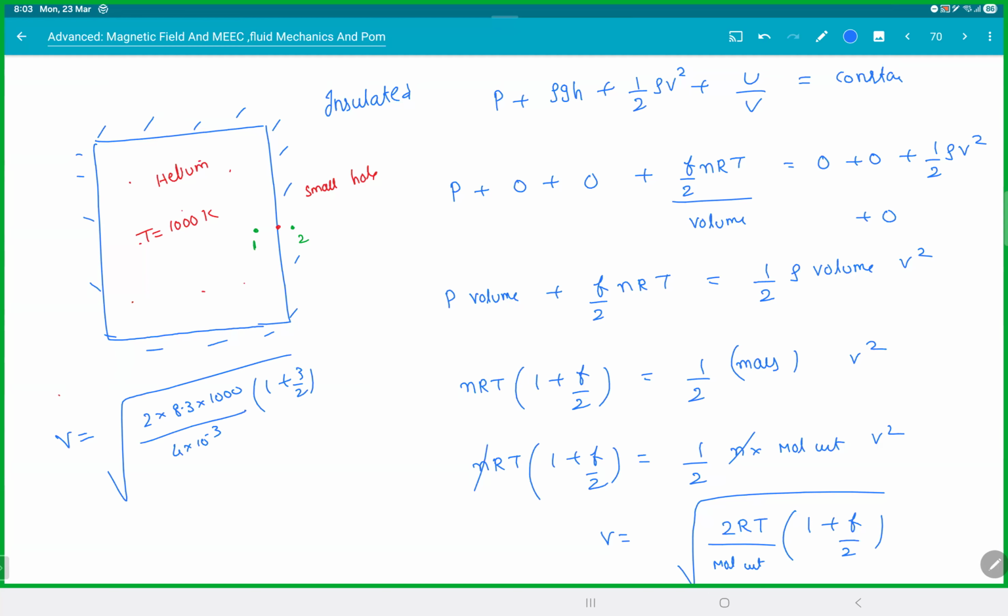So this is actually a question from Meredo, so it's a good one. You have to use the modified Bernoulli. The main idea was that Bernoulli's equation, at the end of the day, is fundamentally energy conservation. So the question here comes: when the liquid is flowing through a pipe, we never cared about the temperature. We assumed it was always constant. So if it is changing, then what?